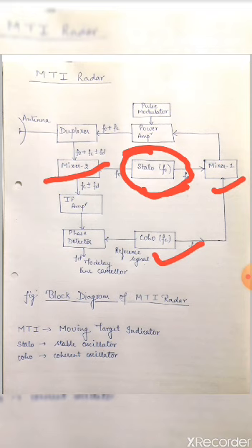If the IF stage is designed as a matched filter, a phase detector is used to mix the signal received from the IF stage and the coho.